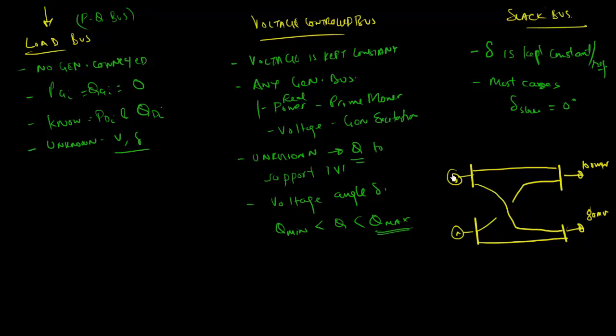Let's say this generator is known. You have this as, let's say, 90 megawatts. Now this load is totaling up to 180 megawatts. You would think that, okay, then this generator also needs to just produce 90 megawatts. But what we don't know is there are losses in these transmission lines. If there are transformers, there'll be losses in those transformers as well.